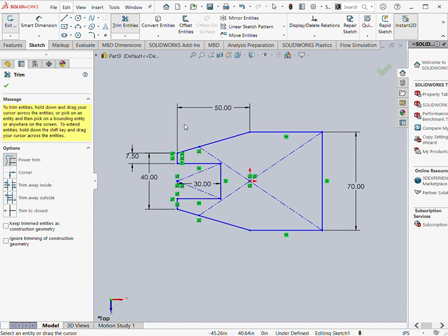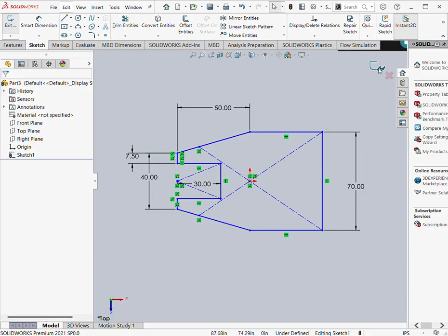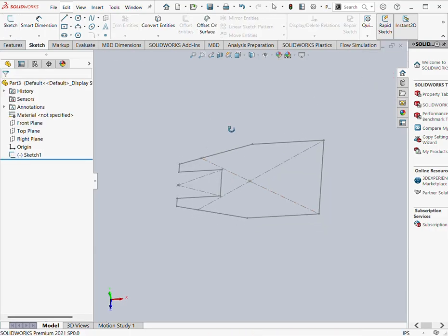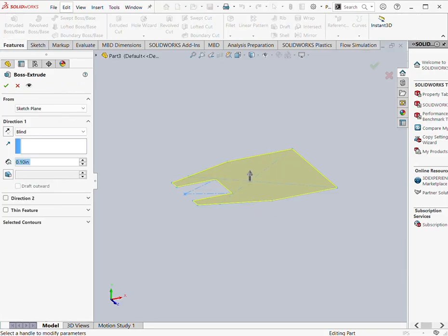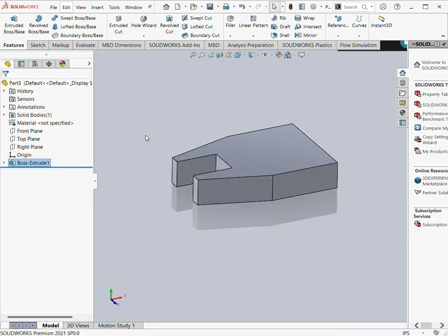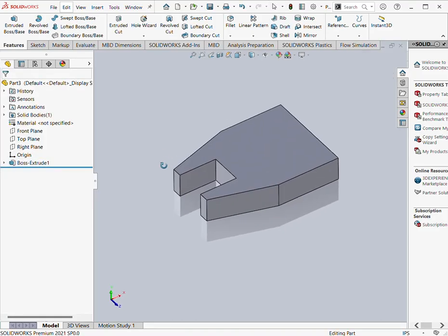Got it? Exit sketch. Choose sketch feature extrude command. How much thickness it should be? 20 units. This lower face, this lower slab would have thickness of 20 units. We'll choose it 20 units. Now you have the lower portion of this part.